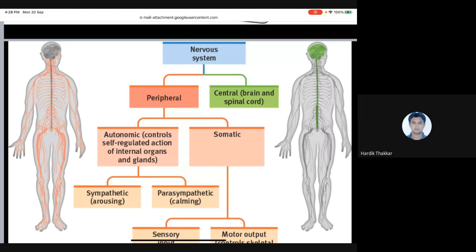And this electrode impedance varies from person to person. Somebody has 10 kilo ohm, somebody 20 kilo ohm. Some people say that the impedance should be below 10 kilo ohm, but please mind it, everybody has their own impedance. My head is different from your head. So you have to take your own judicious decision when you are recording the signal.